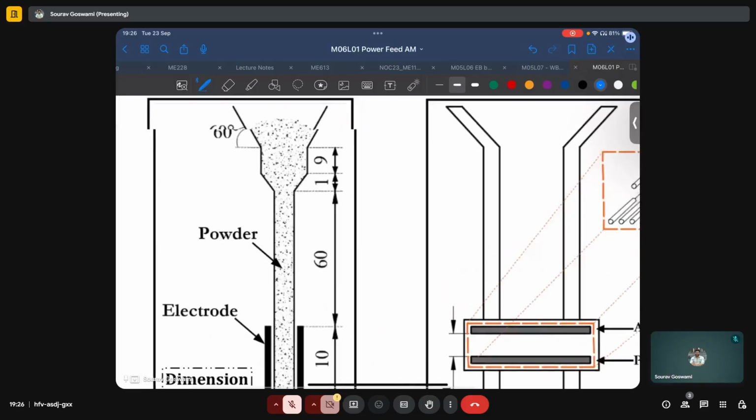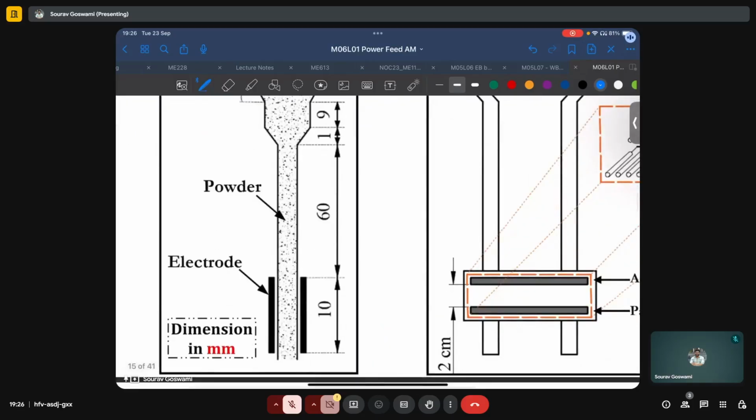Say, for the present example, if the electrodes in this region are suddenly activated, this will lead to accumulation of powder particles affected by the electrostatic field of these electrodes. They will tend to get accumulated in this local region and thus clog or jam the feeder pipe.